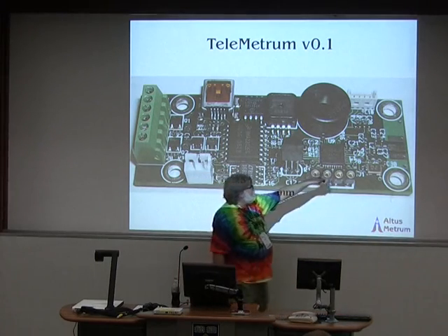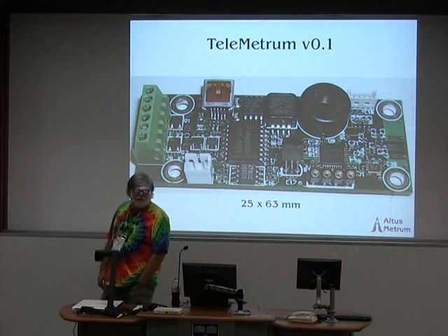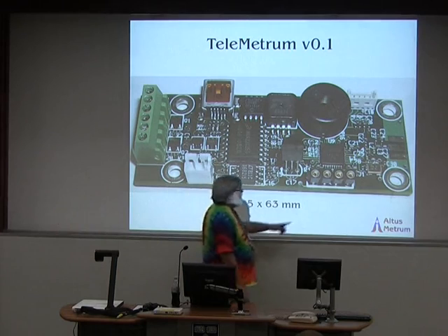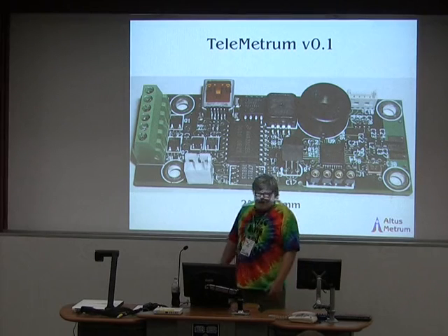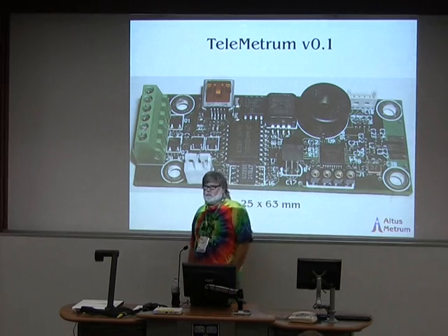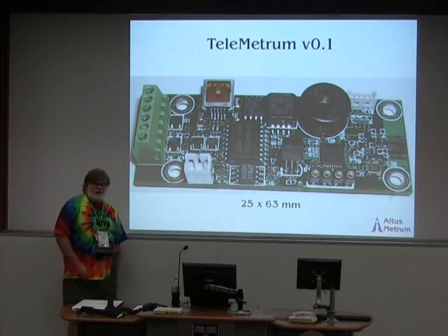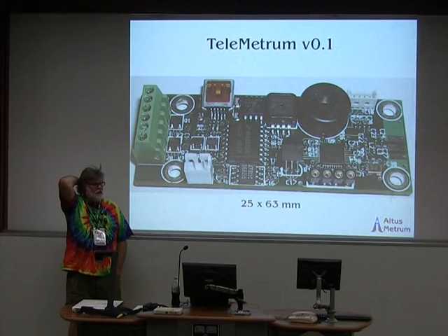That footprint on the end of the board was designed so that an edge-launched SMA connector could be soldered on. But I really have only ever used those in a couple of odd circumstances and for bench testing. Almost always what we end up doing is soldering a wire whip to that center pin and just letting it stick out into the airframe. So we have a quarter wave whip on the transmitting side. The radio puts out 10 milliwatts or plus 10 dBm. Doesn't sound like very much, does it? I forget what the numbers are, but with our current modulation and coding scheme, the theoretical range ought to be on the order of 30 kilometers in free space or something like that.